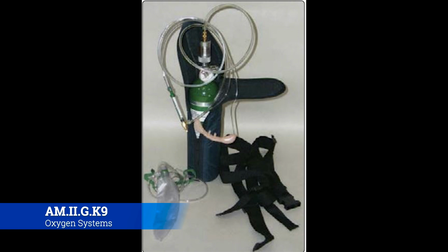Now on top of it is going to sit a regulator. That regulator is basically like a valve that's going to let a certain amount of oxygen come out of the tank as needed. This is a sample of a continuous flow system that you're looking at right now. In its simplest form, all it does is allow oxygen to exit the storage tank, through the valve, and then through a regulator or reducer attached to the top of the tank. That's what that little silver guy is on top of the tank there. The flow of high pressure oxygen passes through the section of the regulator that reduces the pressure of the oxygen, which is then fed into a hose attached to the mask as worn by the user. So effectively, the oxygen leaves the tank, goes through a hose, and goes into your lungs. It's a continuous flow system, and it's fairly simple and straightforward.